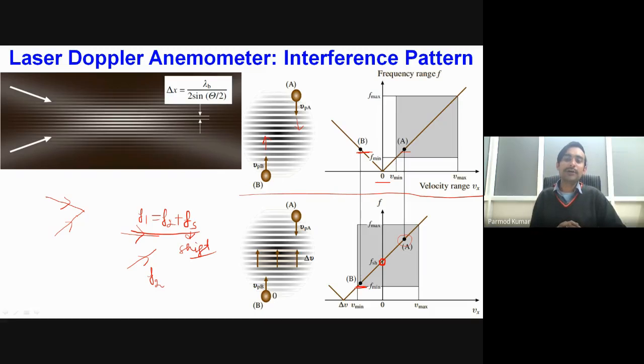Okay, so in order to make this laser Doppler anemometry compatible for determining the direction of the flow, whatever the initial two waves we are considering, we have to initially take some frequency shift between the incident beams, so that we get a moving fringe pattern. Then we can determine the interaction of the particle with the moving fringe pattern in order to obtain the directional dependence of velocity.